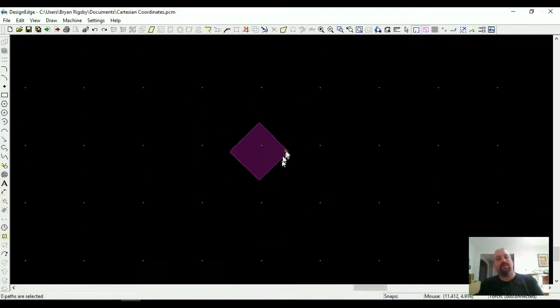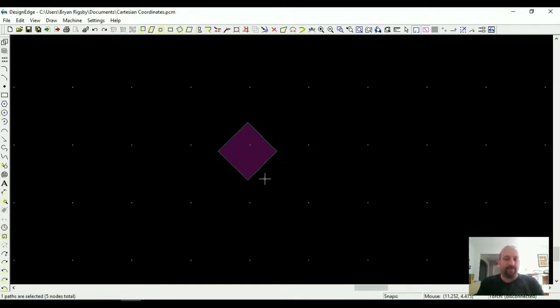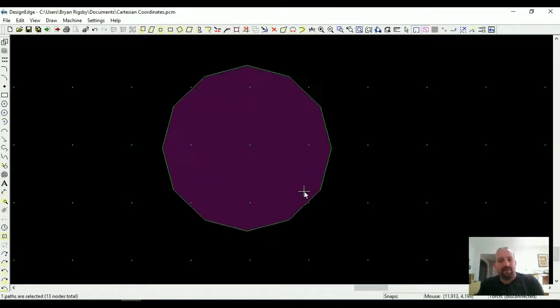So when I set my arc resolution down to 6, that's a circle. I mean, it's still a shape that comprises 360 degrees. But if I scale that up, knowing it's still a circle, now I have a very crude circle. That's 1, 2, 3, 4, 5, 6, 7, 8 sides. And if I scale it up even farther, I'm going to have even more sides.